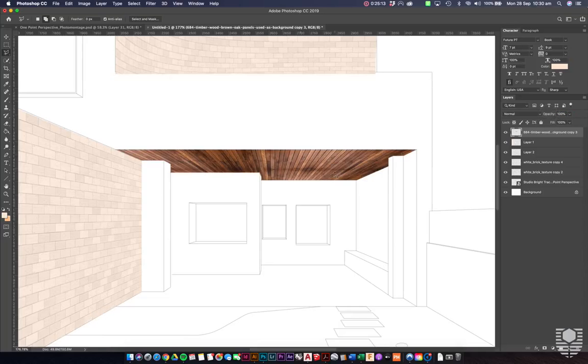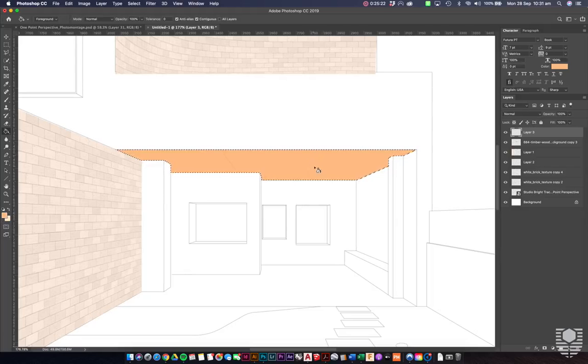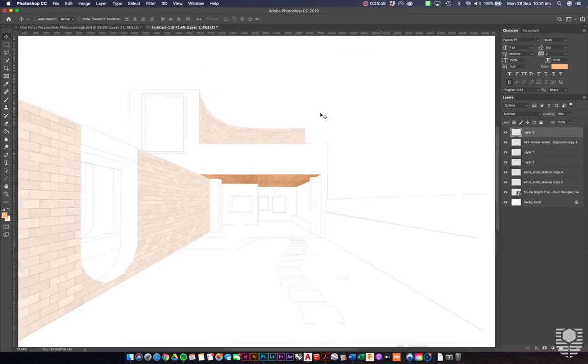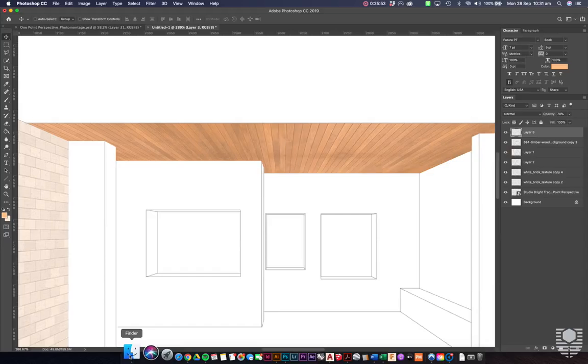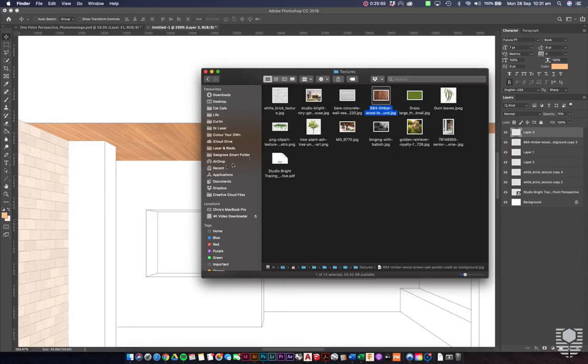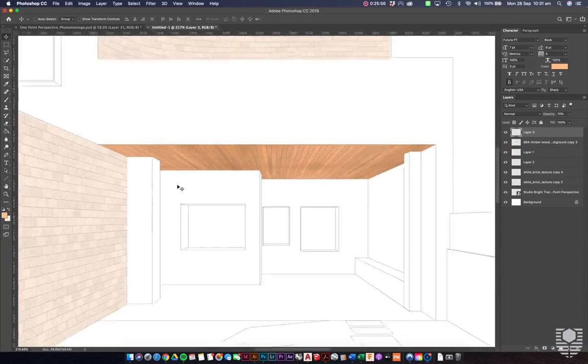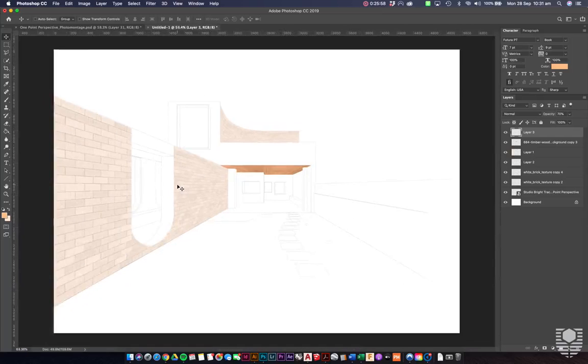But again, we can see this is way too intense a color for what's going on inside there. So, same technique. Create a new layer, select pixels of the timber, go back up to the new layer, G for paint bucket, swap that back to that orange that I liked before, and then I've got that over the top. Bring that layer down, maybe to 70%, and now I have a nice warm orangey timber inside here, which looks great. And then we follow this process over and over again. We continue to bring the textures back in and play with them, and we experiment with colors over the top.